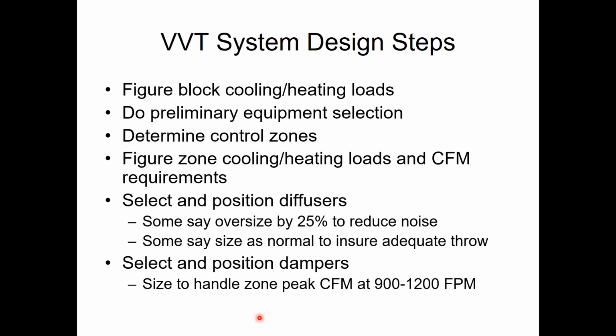In fact, I like it when the damper is smaller than the duct. Sometimes I will intentionally make the damper smaller than the duct. If I have a 12-inch duct coming in, I may on purpose put a 10-inch damper in. And I do the same thing on piping systems for control valves on air handlers. You may have a 2-inch water line coming to an air handler, and I may put a 1.5-inch valve there. And you're like, dude, why'd you send me this 1.5-inch valve? Now I've got to make a transition. Yeah, you've got to make a transition. So what? Big deal.